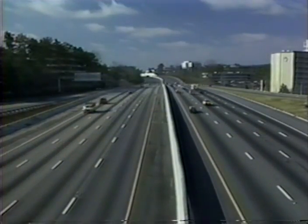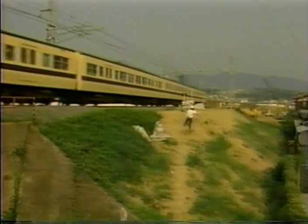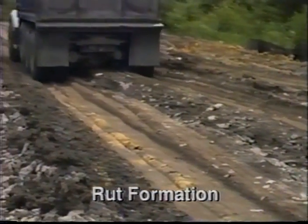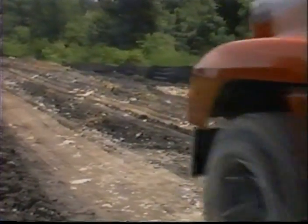In the construction of roads, highways, airfields, and railroads, geotextiles increase stability and improve performance of weak subgrade soils, primarily by separating the aggregate from the subgrade. One characteristic of low-volume roads like forest or access roads and high-volume roads during initial construction on soft subgrades is pronounced rut formation due to high axle loads of construction vehicles. Deterioration of the subgrade due to rutting causes frequent maintenance problems, reduced road effectiveness, and stresses to vehicles.